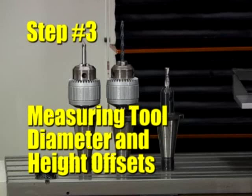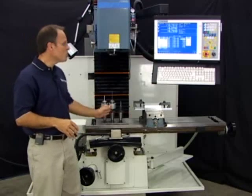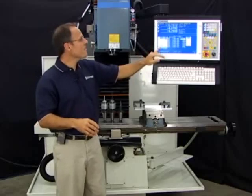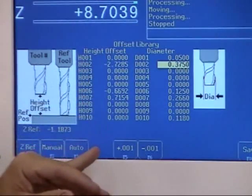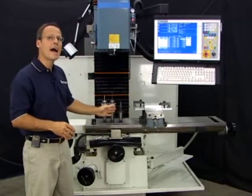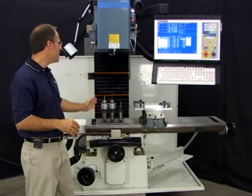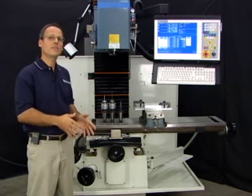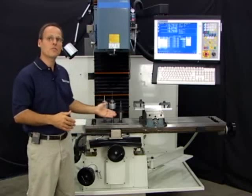Now, even before you go program the part, I want you to get the tools set up in the Centroid tool library. In the tool library, you're going to find two columns, a height offset column and a diameter offset. Each tool that you have is going to have its own unique height and diameter offset. The diameter offset's pretty easy to understand. It's simply the diameter of the tool.